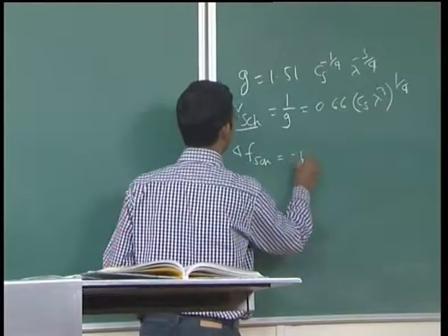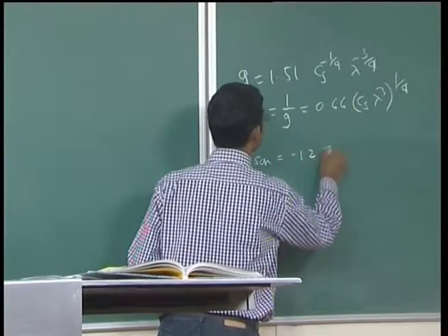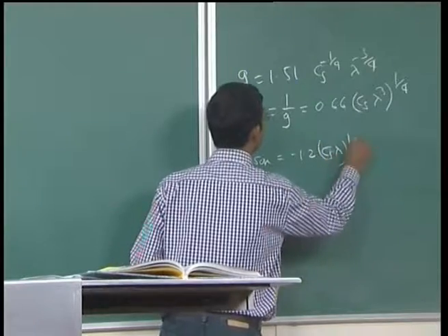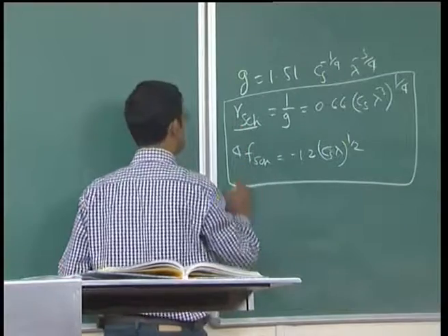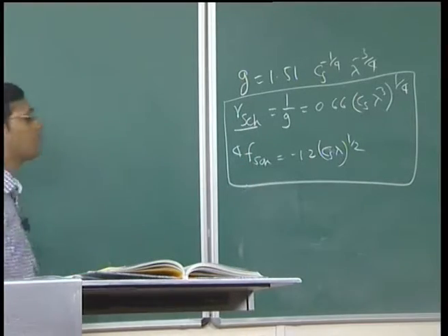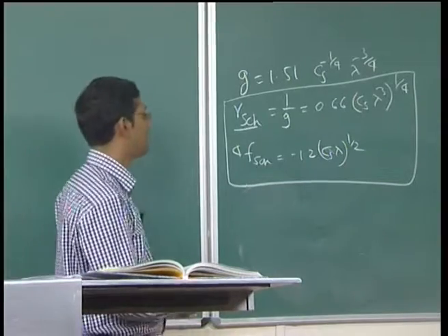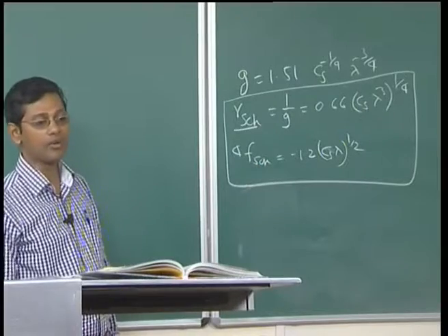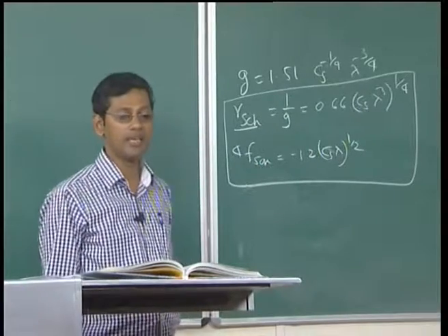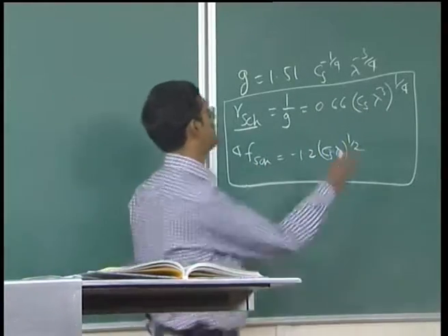Well, therefore, these two functions, one is R Scherzer, another one is the delta f Scherzer, which is equal to 1.2 Cs lambda to the power half. These two are the master equations in high resolution electron microscopy. They give us the limits for any use of the high resolution electron microscope. This was due to Otto Scherzer, and the first equation was basically developed by Glaser.